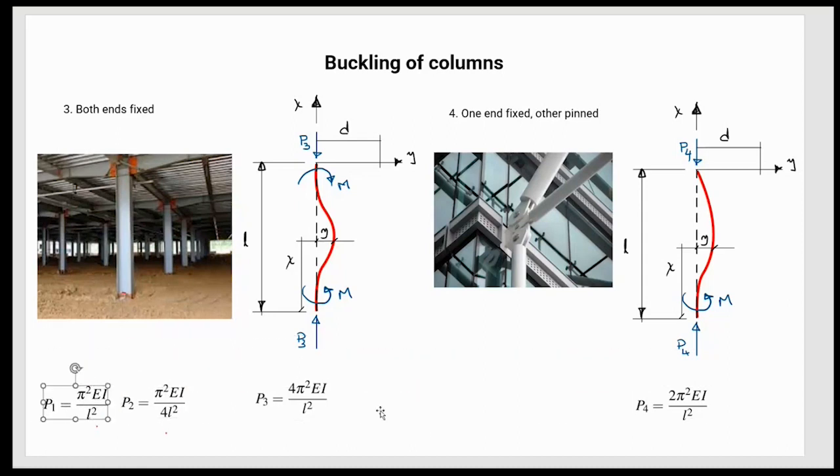Okay. This is for a fixed condition, and look at the way it deforms, because now they have a resisting moment since there are no degrees of freedom in the joints that allow the column to rotate around these two points. They are constrained in all 3 axes if we look at it from the planar case, meaning they cannot move in either translational direction or rotate, they are just fixed, and this is the way they're going to deform.